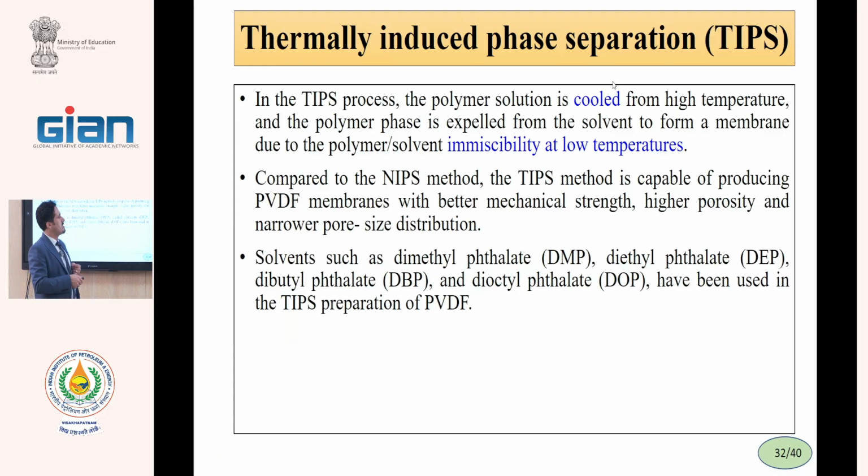is used as a stabilizer in PVC for increasing flexibility. After preparation of PVC tubes, usually 2%, 3% DOP or DBP is added to increase the flexibility and reduce the brittleness of PVC tubes.